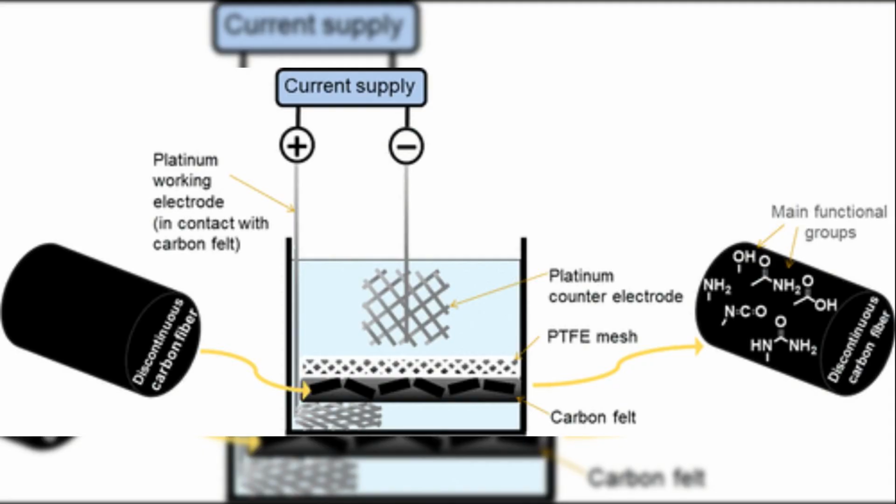To solve this problem, carbon fibers undergo a process known as surface treatment. During surface treatment, the fiber surface is slightly modified in order to improve its chemical reactivity and roughness. This is usually done through controlled oxidation processes. The fibers may pass through chemical baths or undergo electrochemical treatment. These processes create microscopic irregularities and introduce chemical groups on the surface of the fibers.